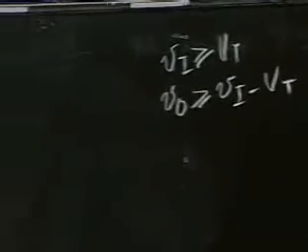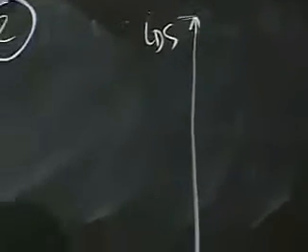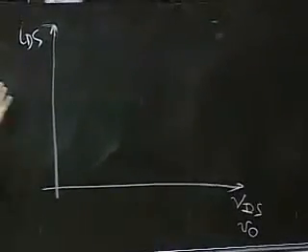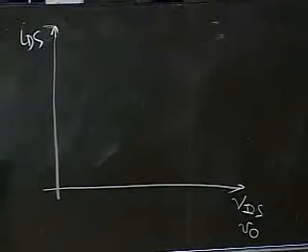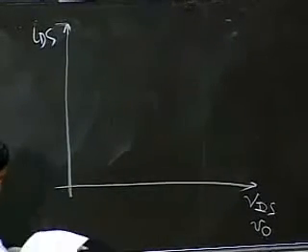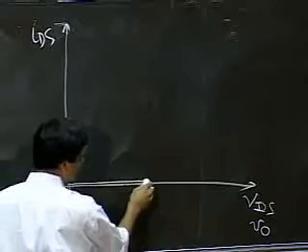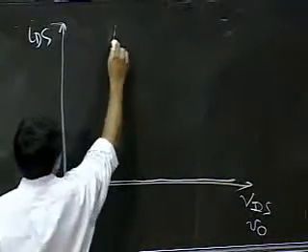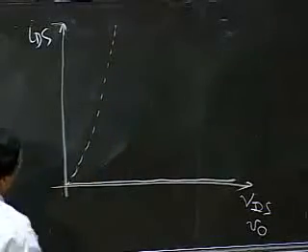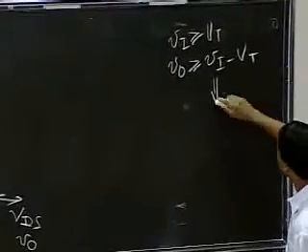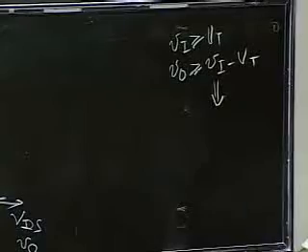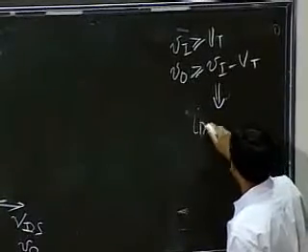Those are my limits. So the way we got the load line graph was we superimposed the load line equation over the device characteristics. And so let me plot the device characteristics in the saturation region. Remember that this constraint could be related to the current, as I derived for you in the last lecture, as follows.